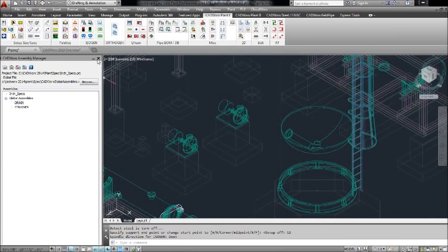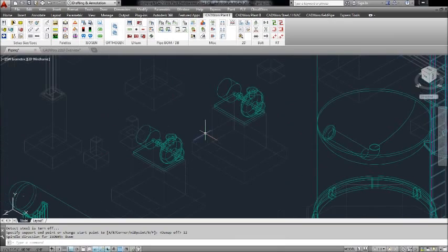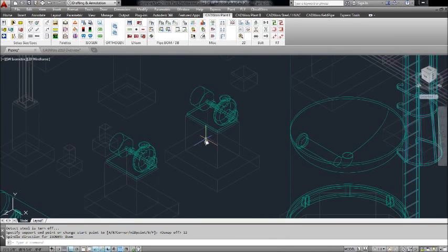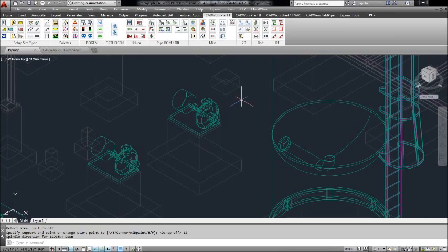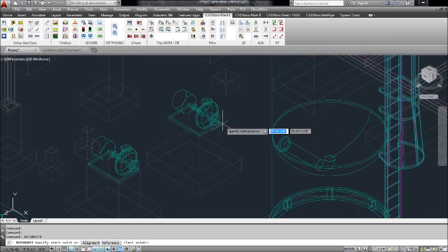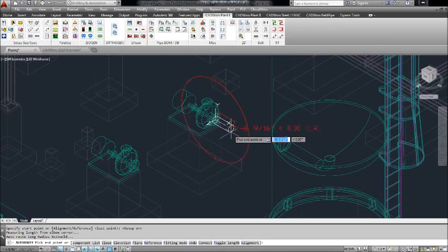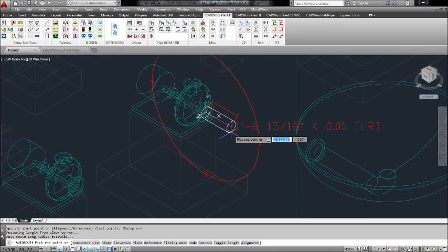Okay, let's look at this pump suction line over here. We're going to use this as an opportunity to display a couple more routing opportunities, different things that we can do. I'm going to reinitiate my router here, and I'm going to grab a node O-snap, and I'm going to grab on this suction line of this CADWorx Intelligent Nozzle for this suction on the pump. And CADWorx recognized what size I was needing because of the nominal size of that nozzle, and I can start pulling out here, but I know that eventually what I want here is going to be an eccentric reducer with fitting makeup to the flange. So I can let CADWorx put the flange and everything else in for me automatically.